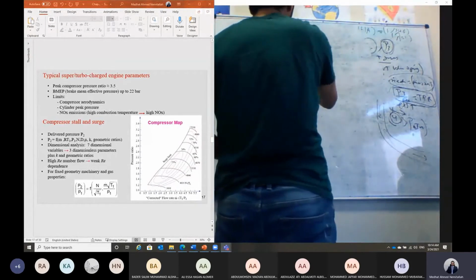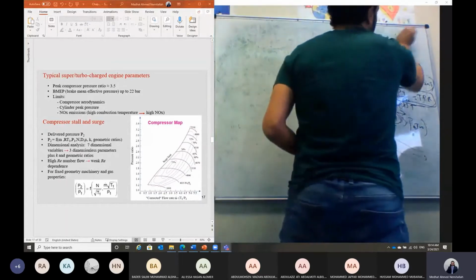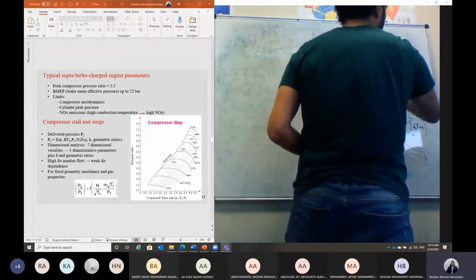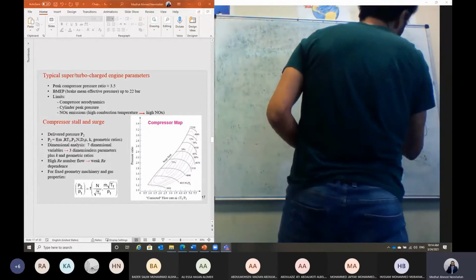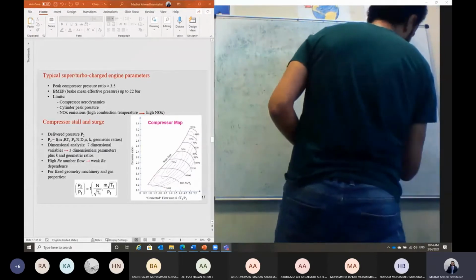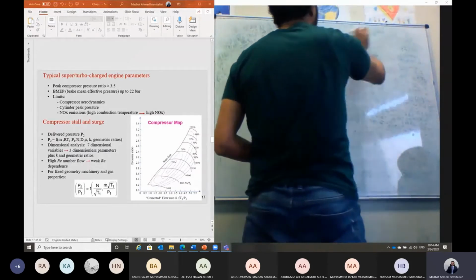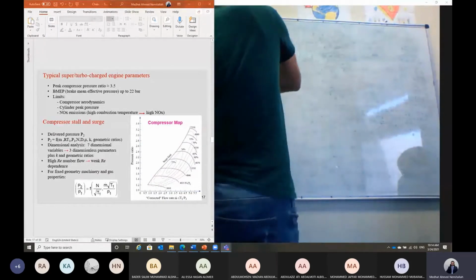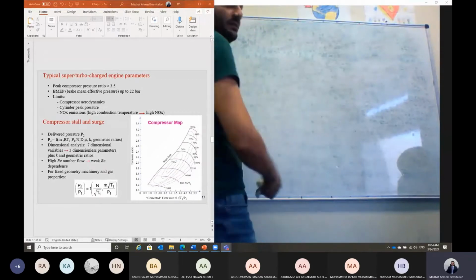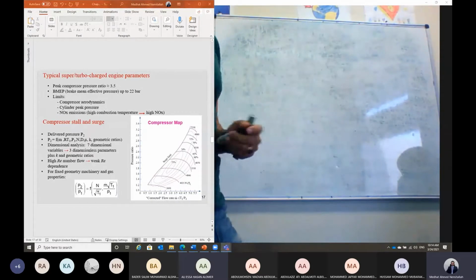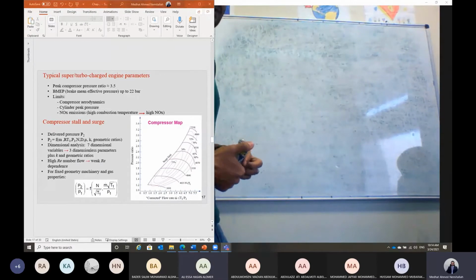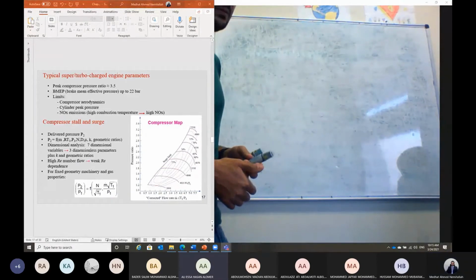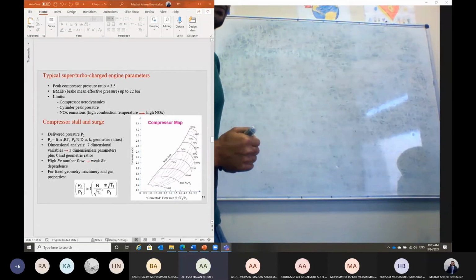Do we have limits like for the case of the gasoline engine? Is it allowed to use a turbocharger under all conditions without any limitation for the pressure ratio across the compressor and for the mass flow rate? Can we increase the mass flow rate to infinity? No, we need to keep it to make sure that the air that gets into the engine is near stoichiometry.